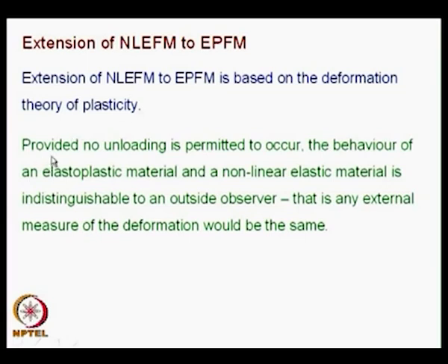So, you say provided no unloading is permitted to occur, the behavior of an elastoplastic material and a nonlinear elastic material is indistinguishable to an outside observer. That we had seen, the loading and unloading paths are same when you are nonlinear elastic, but if unloading is permitted in elastoplastic material, the unloading path is different. So, now you do not permit unloading. For an external observer, it will remain identical.